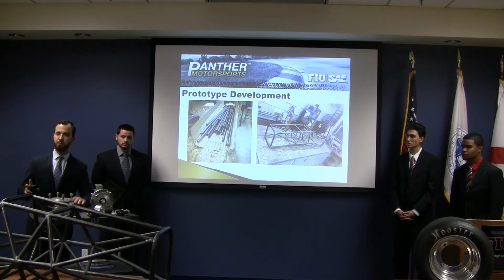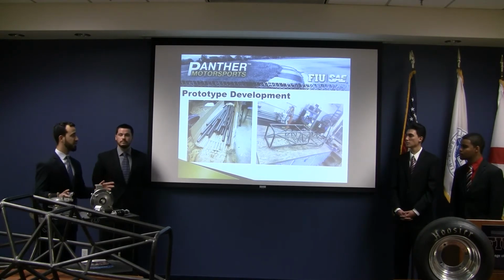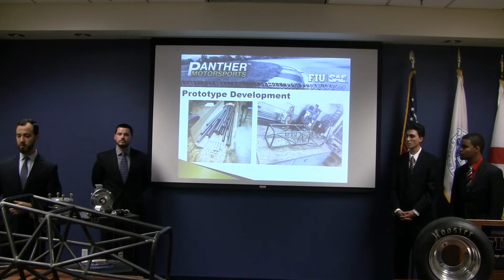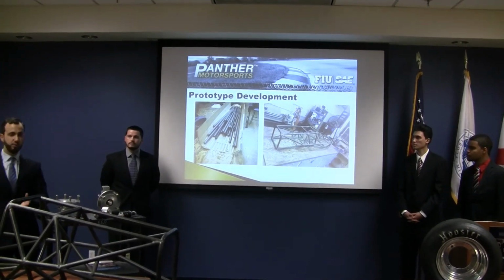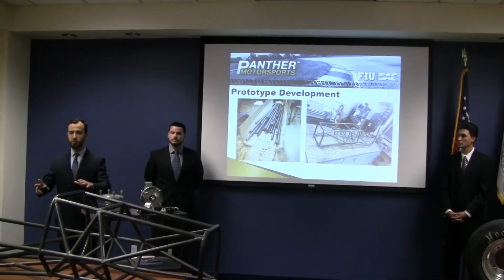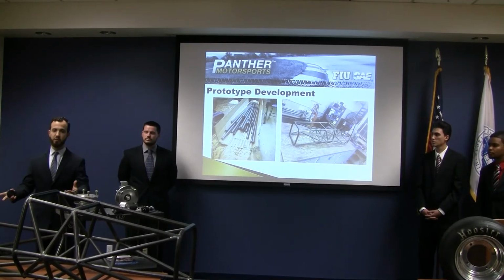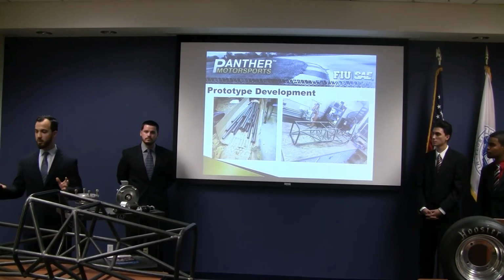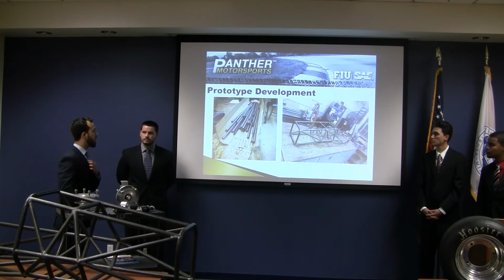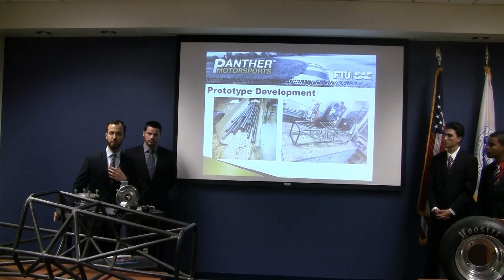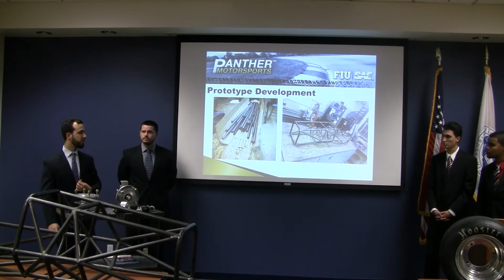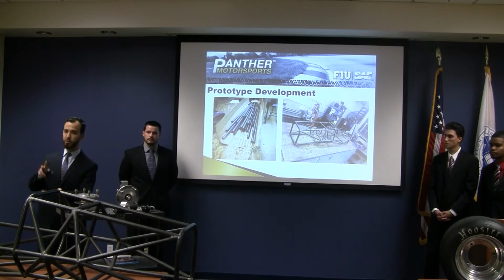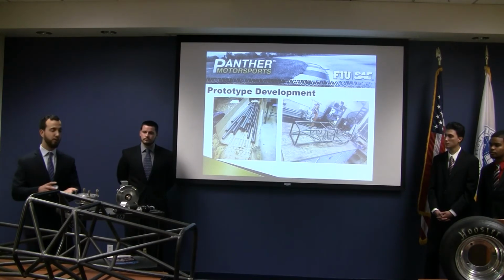And then in-house, we designed and manufactured a jig, which is important when assembling a space frame. You use a common reference point, and you always use the levels and the earth as a reference point, making sure all members are properly aligned. For the suspension, we also will use the same techniques as prototype 1, which is applying all arms to a jig, making sure they don't warp during welding.